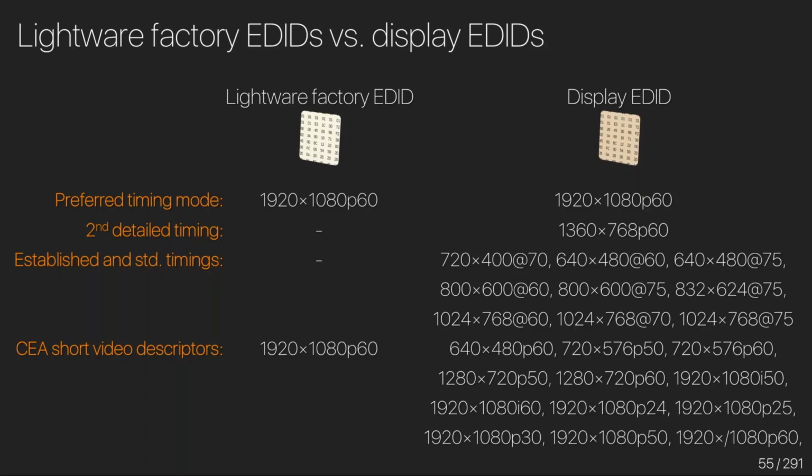The standard for DVI and HDMI says that you can only send a resolution that is listed in the EDID. Like with this display, there's many different options you can choose from, and depending on what source device you connect to it, it might decide to pick a different resolution. So there's a good chance you won't get a consistent experience with this kind of EDID.